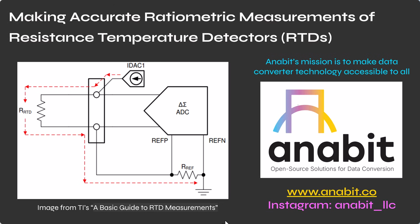This is Neil with Anabit, and welcome to Making Accurate Ratiometric Measurements of Resistance Temperature Detectors, or RTDs. And that's exactly what we're going to talk about in this video. We're going to look at circuit configurations that use a current source, a high-resolution ADC, and a precision reference resistor to make highly accurate temperature measurements using RTD sensors. And these will be ratiometric measurements. And if you're not familiar with that term, we'll define that in the video.